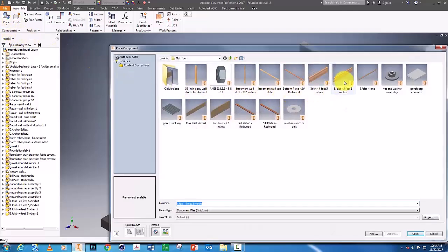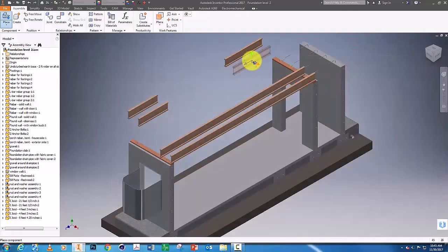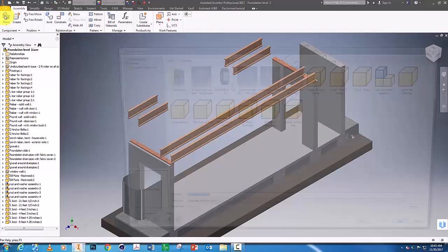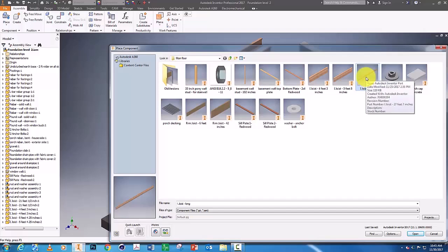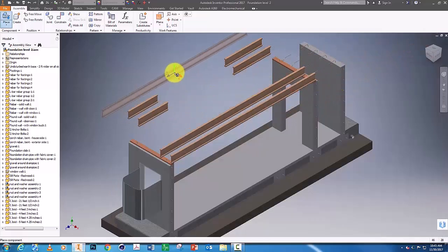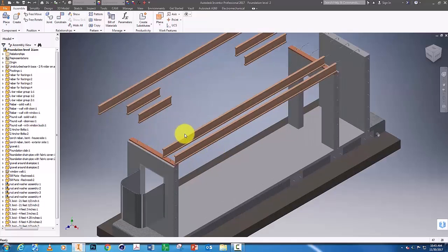And let's place the other side. Those lengths will be 5 feet 5 inches. Place 2 copies of those. And let's place one more full length long I-joist. Now first of all, the width of our stairwell is going to be the minimum. It's going to be 36 inches. So I'm going to start by putting this I-joist 36 inches from this I-joist.